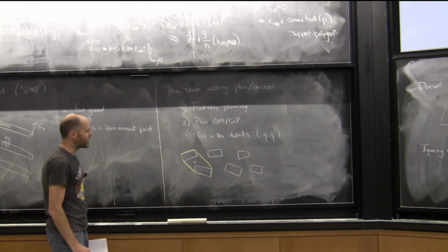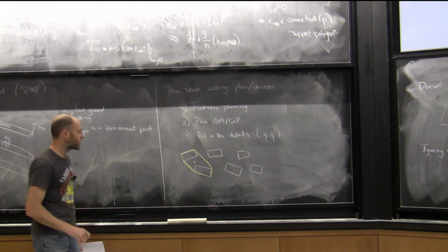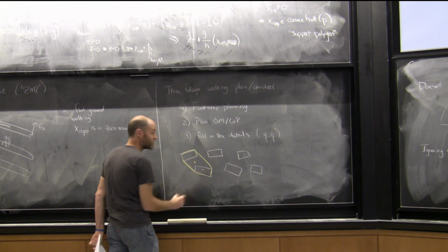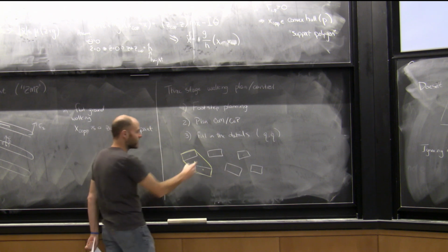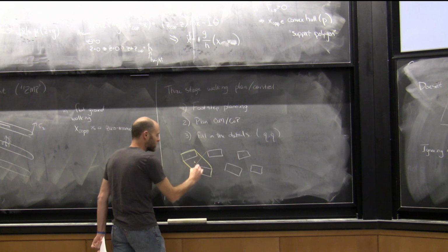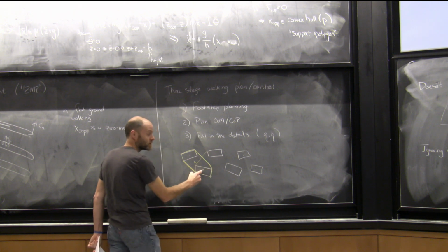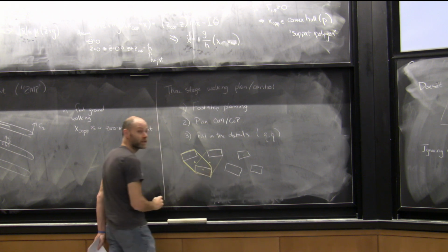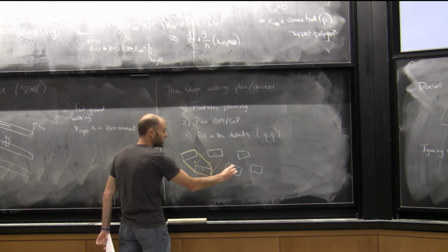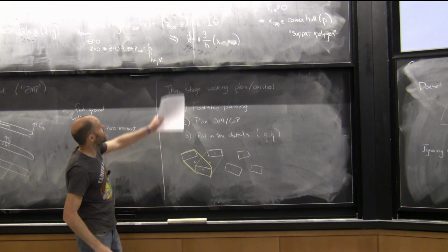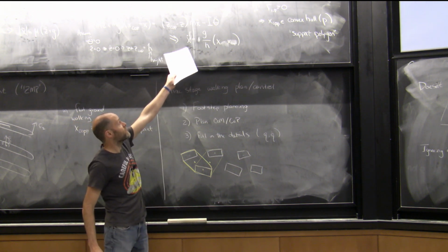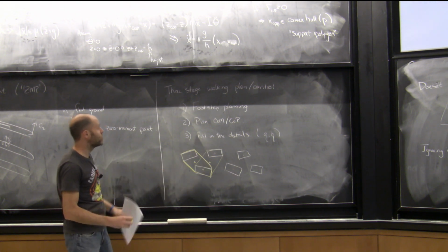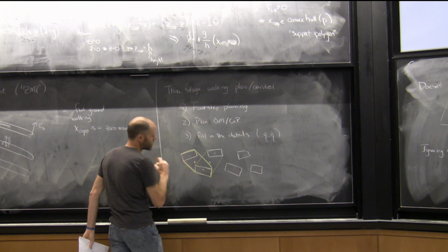Okay? And then similarly, as I start walking, if I lift this foot up, the center of pressure is going to have to be inside this foot. If I put this foot down, then I'm going to have a convex hull that looks like this for a moment. If I put this foot down, I'm going to have this convex hull, so I could have a point over here. And the timing, because these are affecting the acceleration of my center of mass, the exact timing of moving this matters, and I'd like to have a continuous center of pressure trajectory.